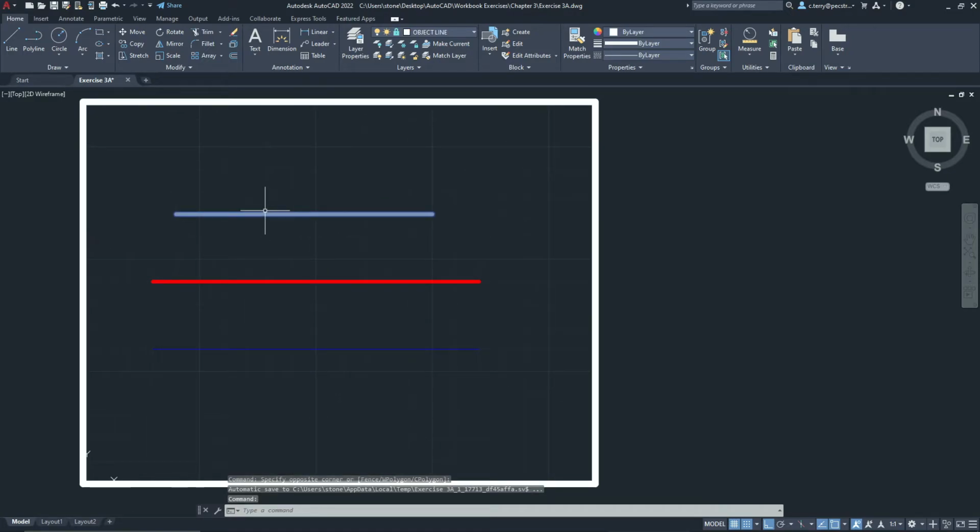So essentially what this is good for is if you get the perimeter of your house done or the shape of an object done and you don't want that to change, but you still need to draw something on top of it, you could lock the layer that you drew it on so nothing ever happens to it. If you get some sticky fingers or butter fingers and you accidentally move something you're not supposed to, this can help keep you from doing that. So it's very, very handy.